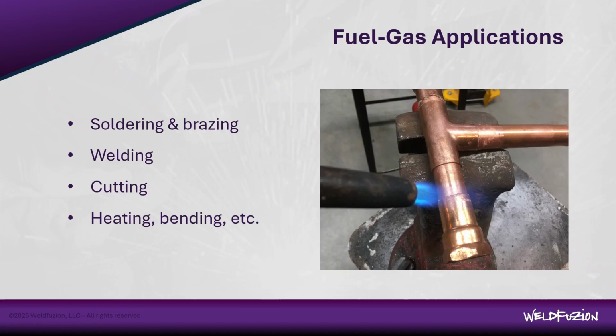And I say tool because it's not just capable of a single process. It's capable of an entire family of processes, ranging from soldering and brazing to welding, cutting, heating and bending, and even more. Oxyfuel is portable and capable of joining many different materials: steel, cast iron, even aluminum.